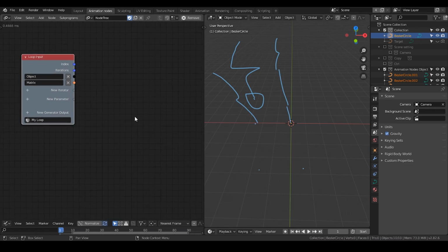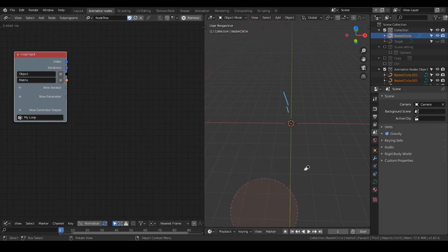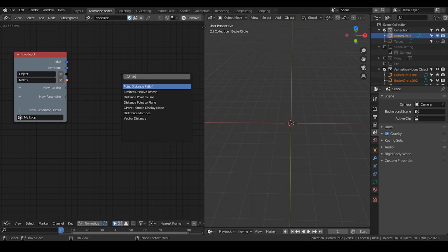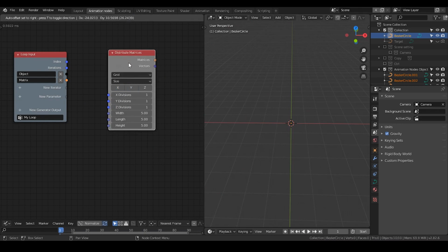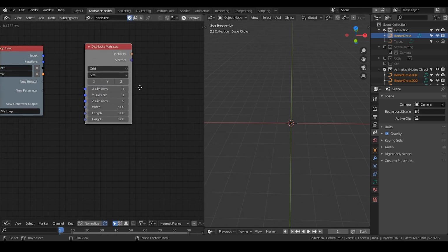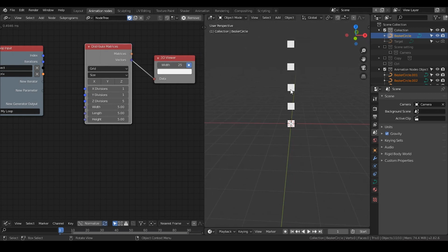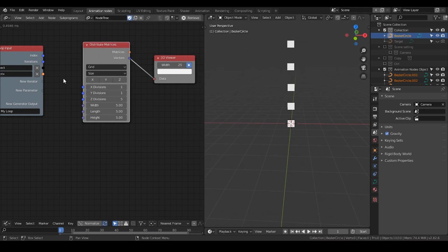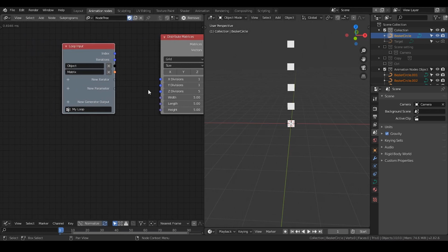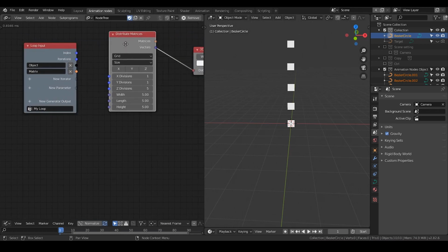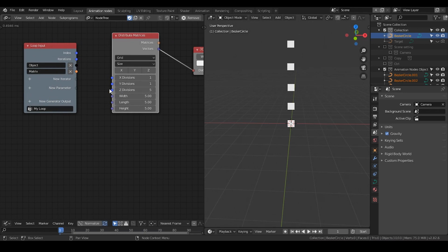Okay. So how to generate a spline that is shooting up to sky, that I have explained in the other tutorials, including the fundamental tutorial, is basically just clean up the X division and make the Z division like 5. So take the 3D viewer, take the vector, as you can see, now we have a spline that is shooting up to sky. Cool. I want different splines to have different lengths. I will specifically manage this later. So far you don't necessarily need to worry about that.